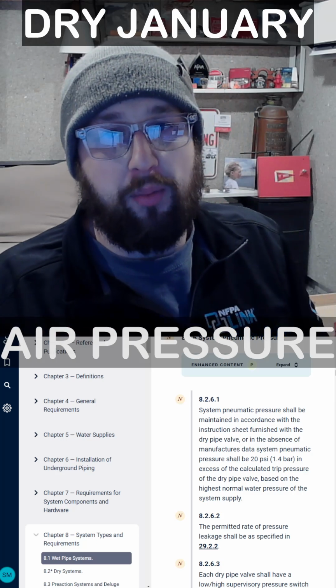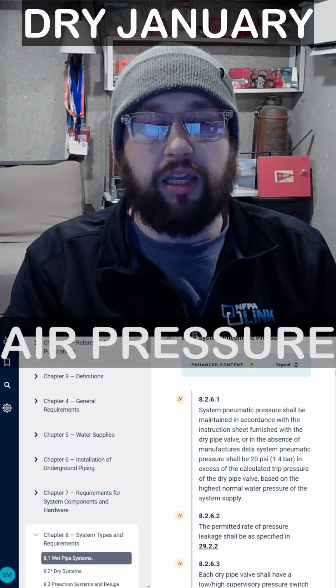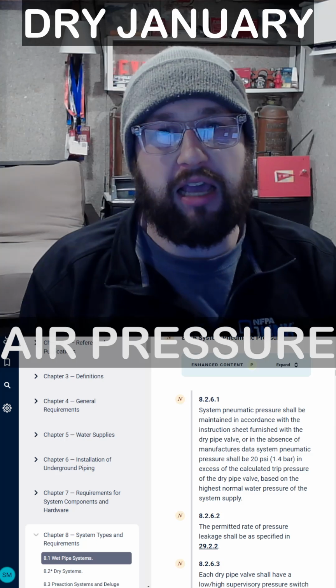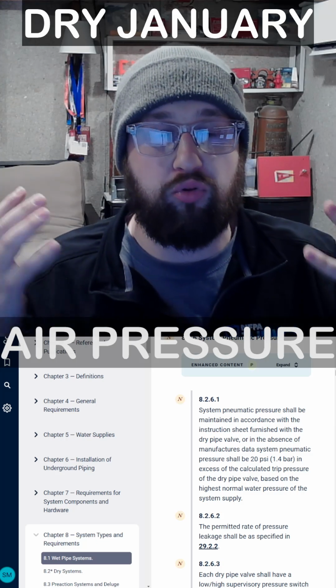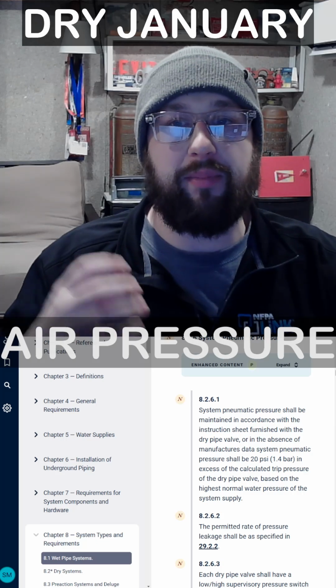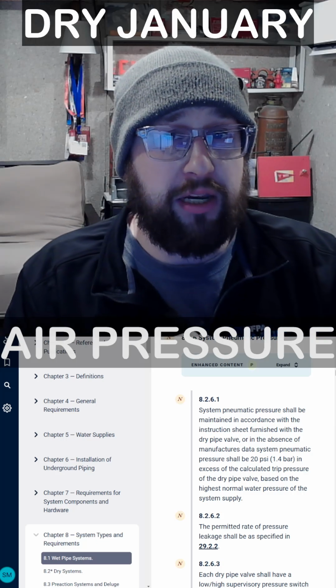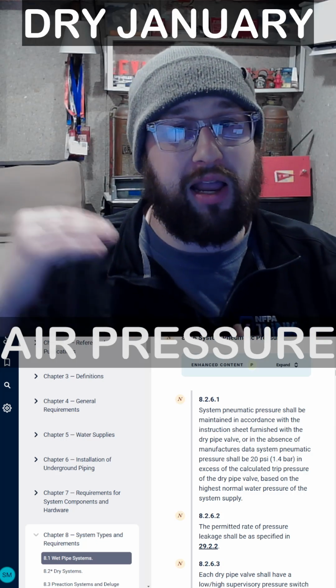So on this installment of Dry January, we're going to be talking about the required system pneumatic pressure in a dry sprinkler system. It's essentially the pressure of the air or nitrogen that we need to maintain in that sprinkler system. And it's important to make sure that that pressure is not too high or too low.